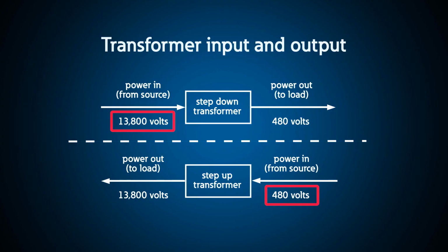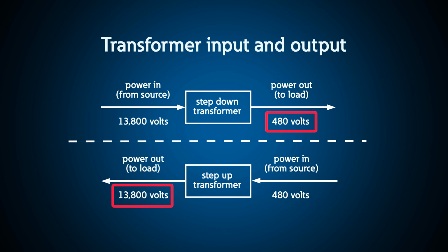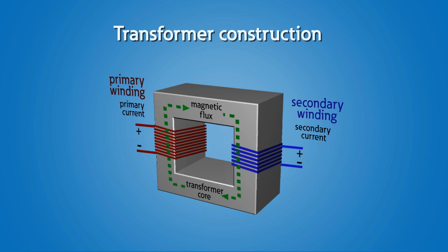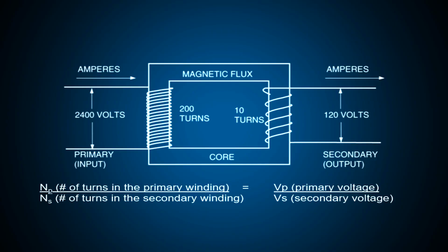The central function of a transformer is to convert the input or primary voltage to a desired output or secondary voltage, generally determined by the needs of the connected equipment. This voltage transformation is accomplished by means of magnetic induction, where the magnetic field shared between windings is equal, but the voltage induced is proportional to the number of turns in the coil.